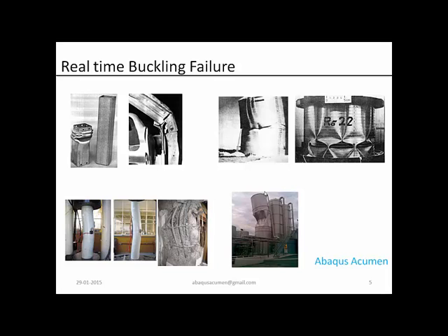For example, in the picture on my top left corner, whenever a car goes through a rollover case, a pillar gets buckled. Or in a frontal crash scenario, crash cans are used to control buckling. Or a very tall pressure vessel can get buckled due to its self weight. Or vacuum pressure vessels, because of the high vacuum pressure, you see some buckling at the bottom.